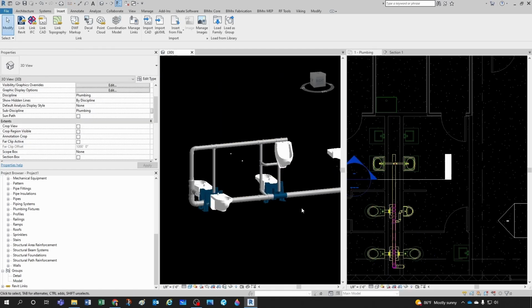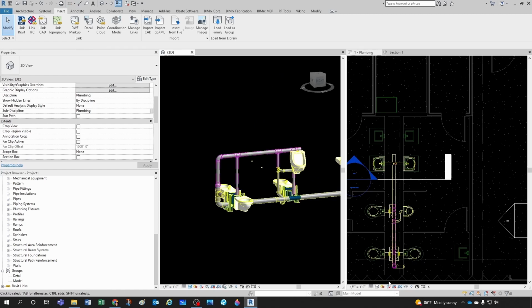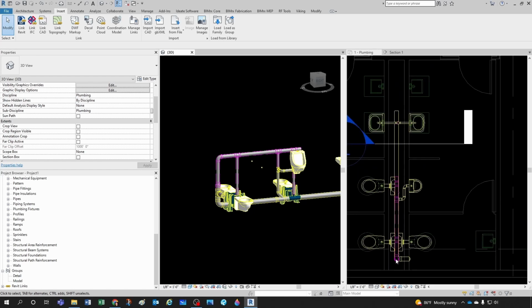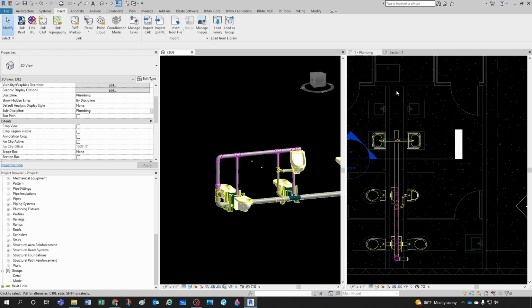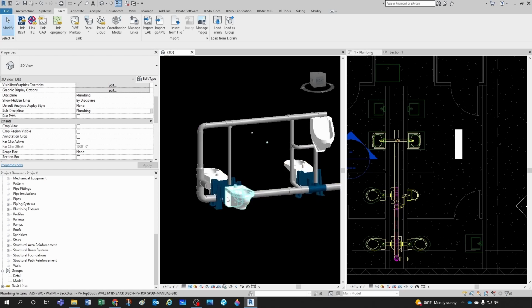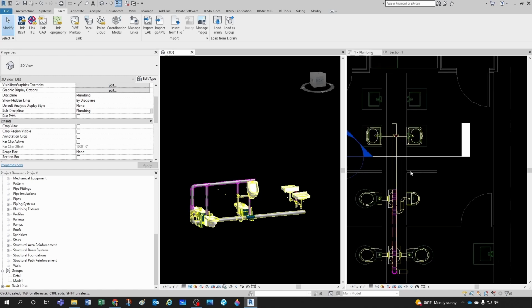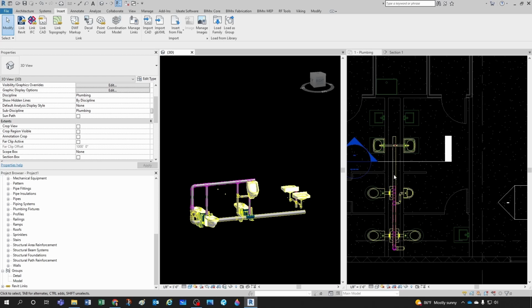So whatever this pipe's going to drop, even from here, which I'm not sloping from here, I'm sloping from here, from this point all the way here, it would be 3 inches. So I'd be wasting all that time sloping and adjusting the elevation of the carriers and all that. Completely unnecessary, because no one's going to be in this chase. It's just me, because I coordinated my plumbing chase with my other trades.